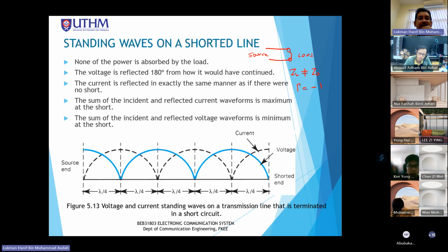So in this case, none of the power is absorbed by the load. The reflected voltage is 180 degrees different from the incident voltage. While the reflected current has the same phase as the incident current. There's no phase reversal from the current perspective.